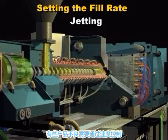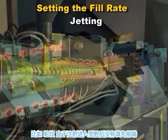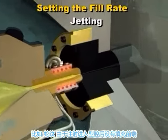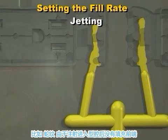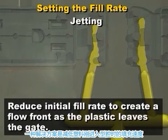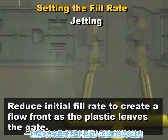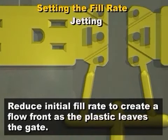Some situations may require fill rate adjustments. For example, jetting is caused by plastic squirting through the gate and not forming a flow front at the start of mold filling. One solution to jetting is to reduce the initial fill rate to create a flow front as the plastic leaves the gate.